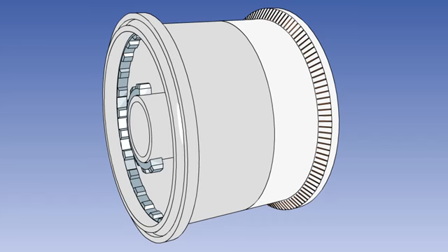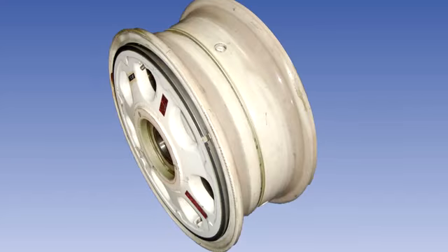Wheels are often produced with a knurled flange. The inner face of the wheel flange is milled, so that the side pressure of the tyre locks the tyre walls to the flange. The wheel rim is tapered, so that the flange area is of greater diameter than at the centre of the rim. When the tyre is inflated, the side pressure forces the tyre outwards to grip the rim.